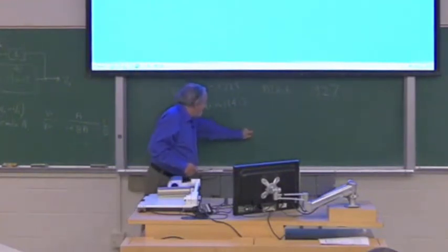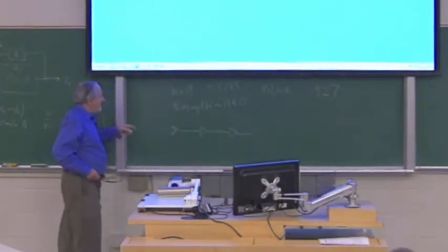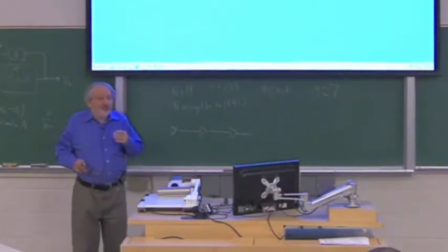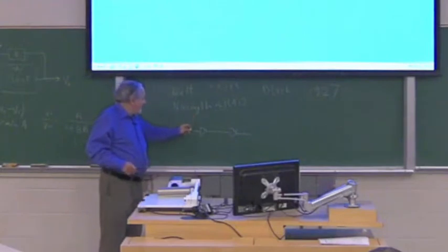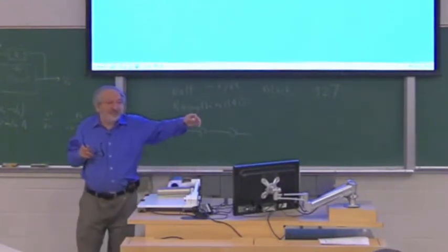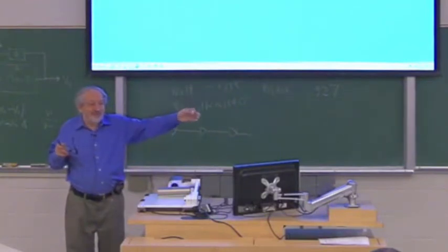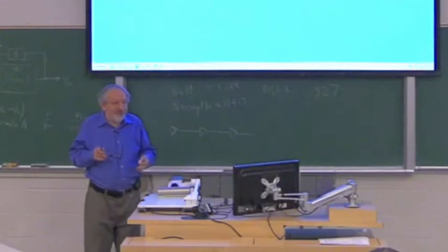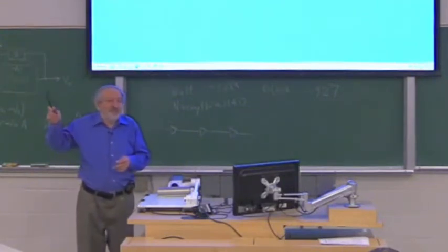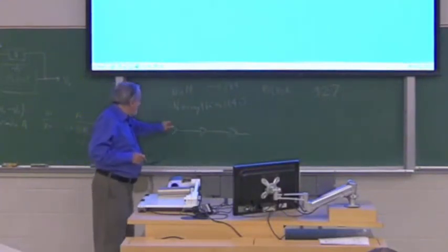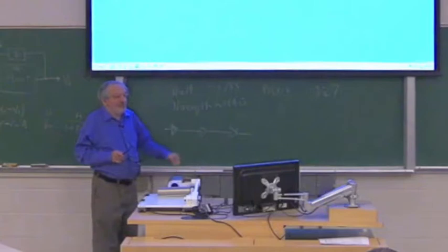And you have big problems. Problem number one, the total gain was very unstable. Because if you patched in at some place, or if the amplifiers drifted, since you had like 100 amplifiers in series, the total result was very unstable. If each amplifier changed 10% with time or temperature, you could have hundreds of percent change at the end. And the second problem was a bit of distortion, because if each amplifier distorts the signal a bit, at the end you get more and more distorted.